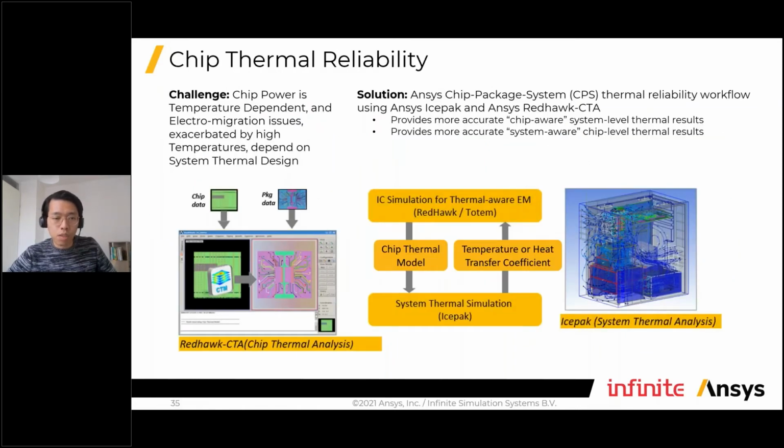That particular Ansys tool is Icepak. But if you are doing chip level, then that's RedHawk, which can help you understand inside the chip how the heat is going to be distributed and how you can improve your design. We're going to spend a little more time on Icepak because it handles a much wider scope, from the chip package all the way to a full data center.